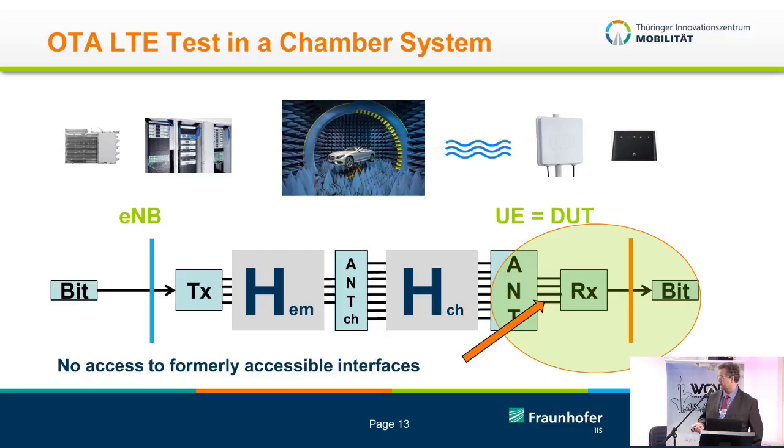Inside the laboratory, we typically do not use the original antennas at the transmit side, but we use a set of, here's a nice Stargate style setup, a set of antennas that are inside the chamber. They are notoriously different from the ones that you originally have. And to drive these antennas, you typically put in some sort of channel emulation device inside your laboratory, which you electrically connect to the transmitter, which then is connected to the antenna.